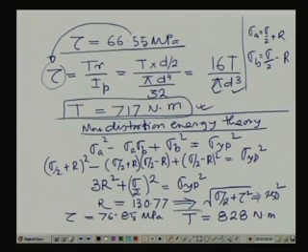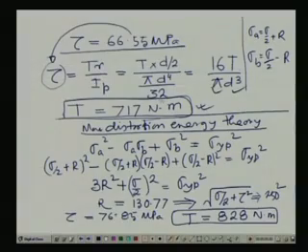Fine. So, you see we got a value of tau from one theory and another value of tau from the other. As we have seen from our earlier plot and these expressions, it is obvious that the maximum shear stress theory is a little more conservative compared to what we get from the maximum distortion energy theory.